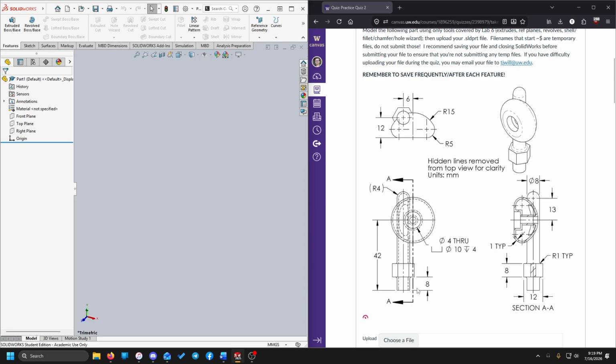At the start of our object, we do see that we've got some hollowness to it. We've got a TYP here, which stands for typical, and that sets a default thickness for our object. So that's probably a shell thickness. We see that the main cylinder on the back of the object is hollow. The earpiece itself is hollow, but the hole wizard that goes through it, based on the hole callout here, seems like whatever happens with the shell adds the wall around that hole wizard.